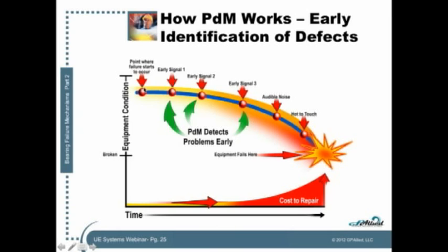Now this is a simple artist rendition of those signals. We'll get a little more specific here in a moment. But you can imagine the subsurface fatigue beginning here, the subsurface fatigue getting worse here, it moving to spalling here, the spalling starting to propagate around the bearing here. It propagates to the point that we can hear the bearing roaring with just our naked ear. Propagates to the point where things are heating up, the bearing's hot to the touch, and then from here maybe it locks up, maybe it loosens up. Hard to know without knowing specifics about the bearing.